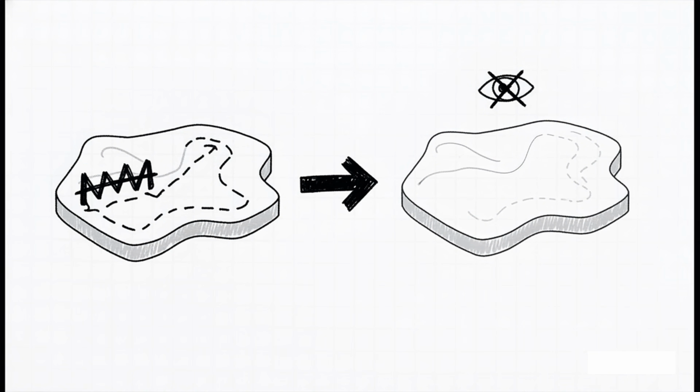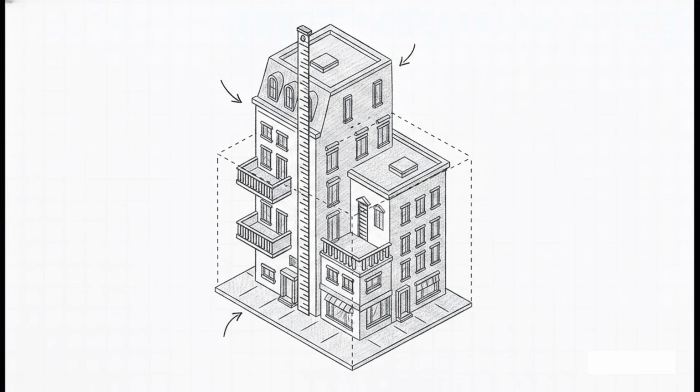So just remember to keep your 2D plans and 3D plans conceptualized in their own respective layers. But honestly, what you lose in 2D lines, you more than make up for with the unique tools you unlock in the oblique view. Here, you aren't just drawing flat shapes. You can draw actual height and width. You can trace 3D lines around existing complex structures. And most impressively, you can measure exact floor-to-top elevations of real-world buildings directly on the map itself.